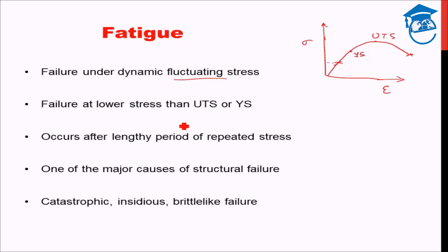In case of tensile kind of failure, the material actually has some plastic deformation going on inside it, which can be externally visibly seen, that there are some changes going on. But if there is no plastic deformation, as can occur in the case of fatigue, then you do not have any indication that the material is actually weakening from inside. Therefore, it can be catastrophic, and for that same reason, it is very important to know the fatigue life of a given material which is used for a structural application, so that we can predict beforehand how long the material will be working properly and when maintenance work needs to be done on the material in order to avoid such catastrophic failure due to fatigue happening within the material. Okay, this is one of the reasons that we need to understand this.